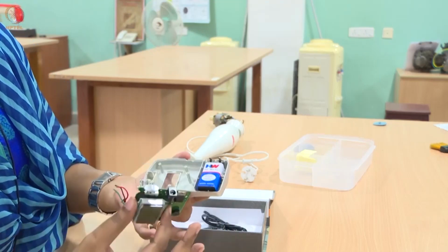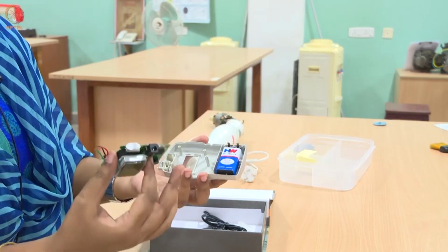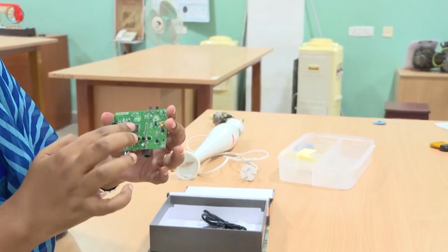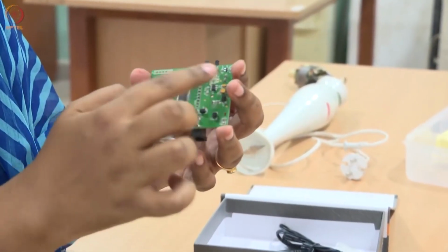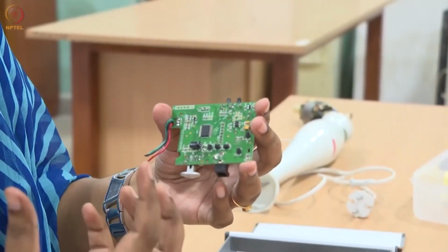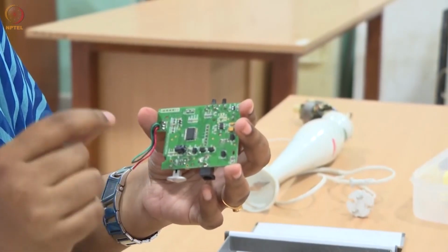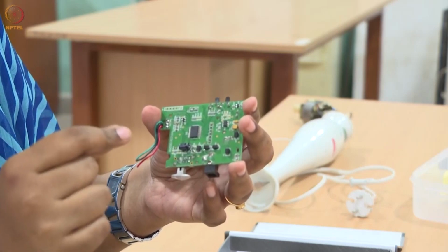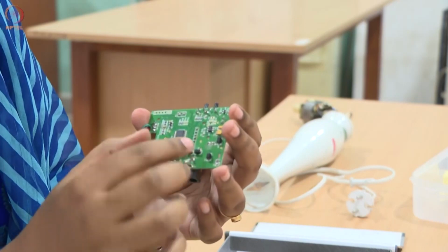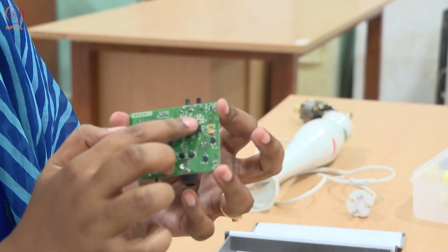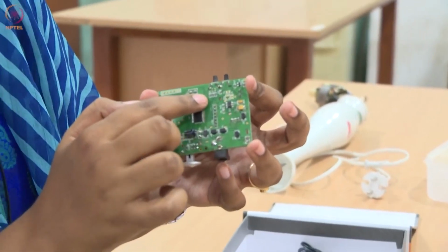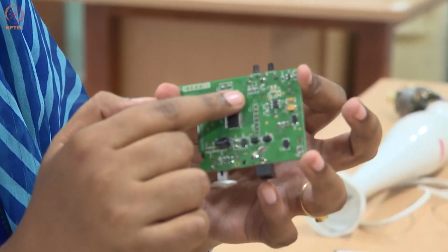So you see that the entire thing just consists of 2 or 3 components because everything has been grouped together. All the components have been grouped together. If you see here, all of these extra resistors that you are seeing on the PCB board are not similar to the ones that you use in a general laboratory session, right? There are certain package numbers which are used. So 0805, actually these are smaller than the 0805 package. So if you see, there are very small resistors and capacitors. And soldering of this is a very tedious task and you need great patience to do the same.